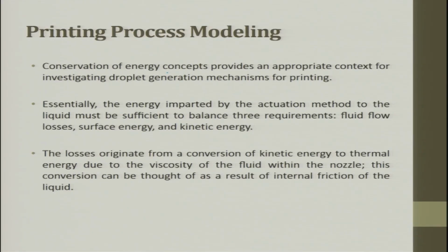The conservation of energy concept provides an appropriate context for investigating the droplet generation mechanism for printing. So, this is the important point, droplet generation. Essentially, the energy imparted by the actuation method to the liquid must be sufficient to balance three requirements: fluid flow loss, surface energy, kinetic energy.